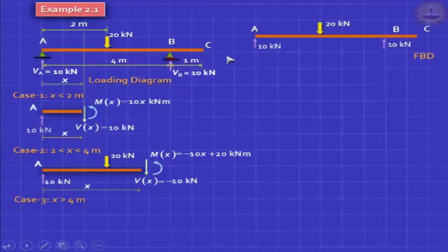But now you have one more section here, but don't waste your time. Here, don't cut a section from the left. That's stupid. Wasting a lot of time. Why don't you conveniently cut from the right side? Always when you see a cantilever or an overhang, go to the free end. That's it. Stay with the same definition of X, but the total length is 5.